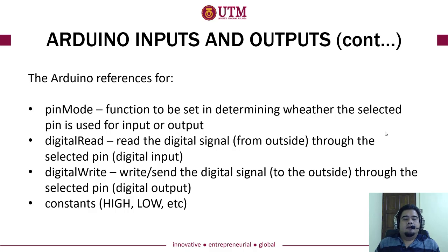For example, there's one function there, pinMode. You need to use the pinMode function in order to operate the input and output ports, because the purpose of this function is to determine whether the selected pin is used for input or output.